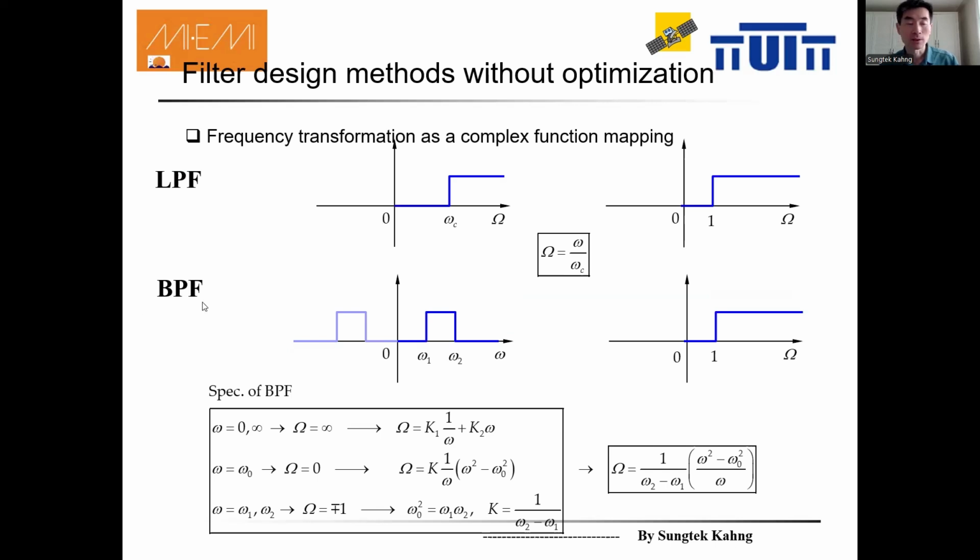Before taking the next step on a bandpass filter, what you do is the low pass filter type prototype. Low pass filter prototype means the frequency is not an absolute value. The capital letter omega means the normalized frequency, as you see. So this is the starting point.